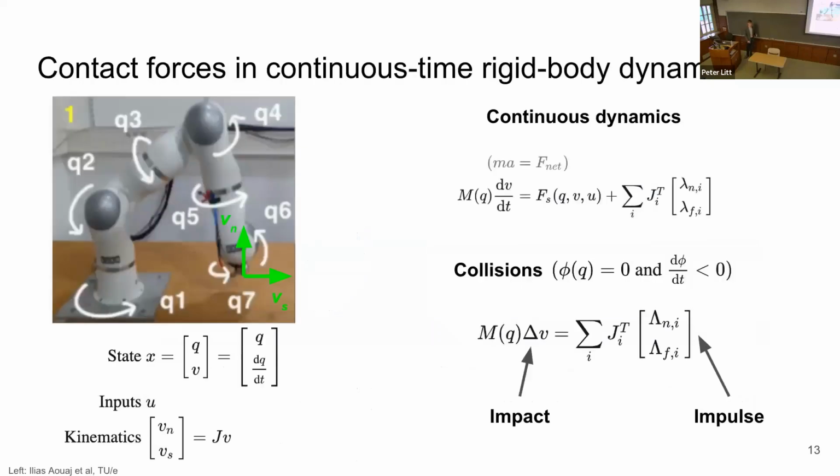So when we want to embed these physical concepts into a computational environment, like a rigid body simulator, we have to be able to handle something more complex than just two objects touching each other. Namely, our robots are often articulated and have inputs such as motor torques affecting their motion. And in general, these models combine joint angles and positions of bodies in the environment into some generalization of Newton's second law, F equals ma, where particularly there are leverages coming from geometry that tell you how those individual contact forces affect the velocities and angular accelerations of all those articulated joints in your system.